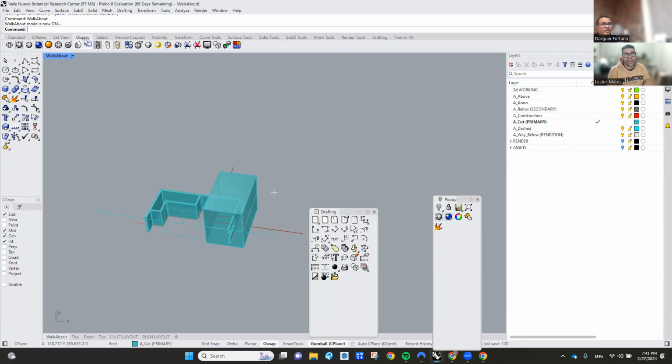What happens if I have 2 floors? That's the last question. Well, if you have 2 floors, you're gonna set your section plane, cutting plane in different direction to show the different floor plans. And then I just put them on a viewport. Well, you're gonna do a make 2D of that view to create your floor plans off of it. Okay. Got it. That's awesome. And then you're gonna bring those floor plans as make 2D. You're gonna export them after you group the lines.